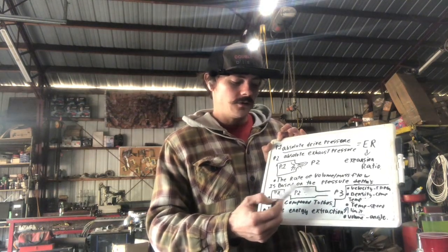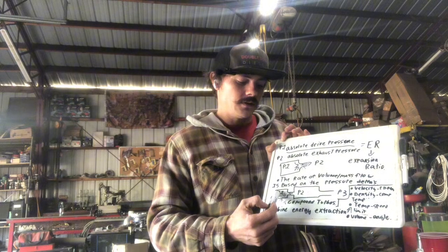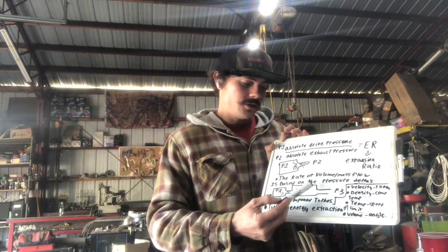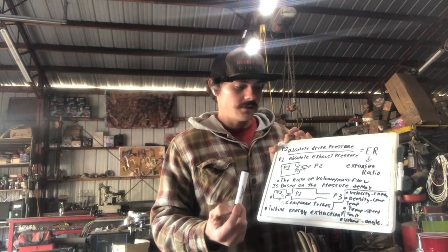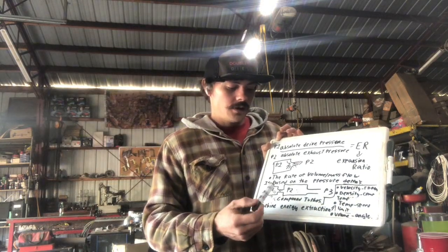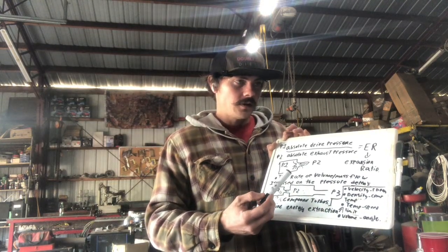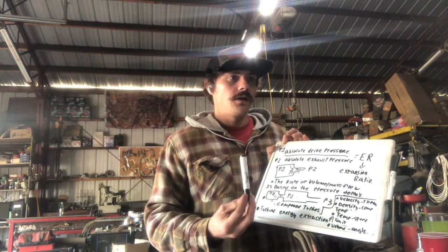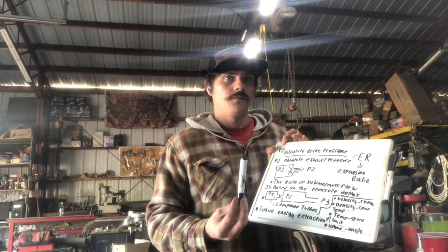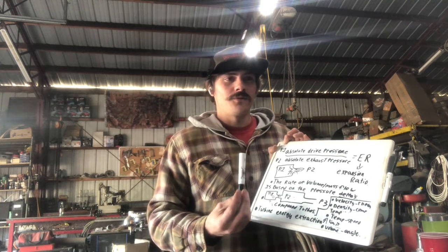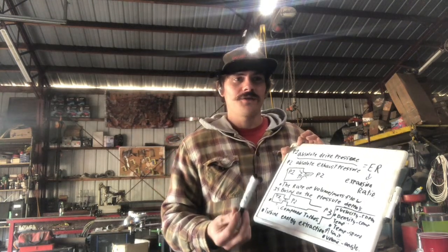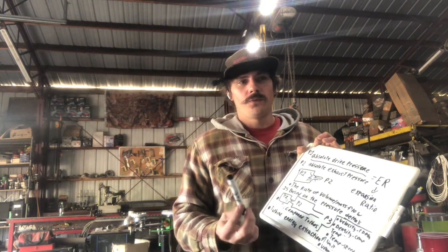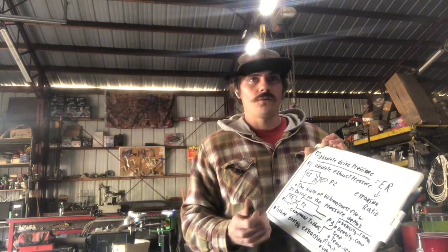And no matter where you adjust the gate on this thing, it will have the same drive pressure and want to make the same boost pressure. And there's a lot of other domino effect stuff that happens that's no fun. But that's how I've been sizing compounds for a little bit, and it's working awesome. It's either working good, meaning it's close to ideal and sometimes they need revisions, or it's pretty dang close to what we're after.